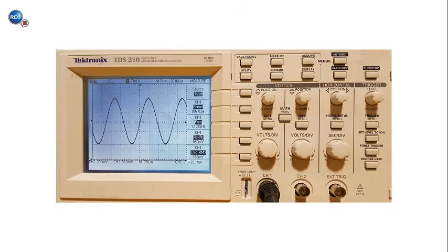This is an image of the oscilloscope from the lab. Here you see a sine wave, and you can see down here at the bottom left it says that channel 1 is set to 200 millivolts. That is the millivolts per division, or the volts per division setting. You can adjust that here. If you turn this knob for channel 1, this is going to zoom the image in and out in the vertical direction. The seconds per division knob is the same for both channels. There's only one. That will zoom in and out on the horizontal axis.